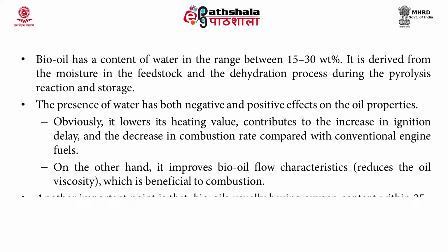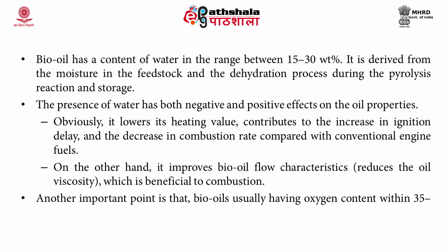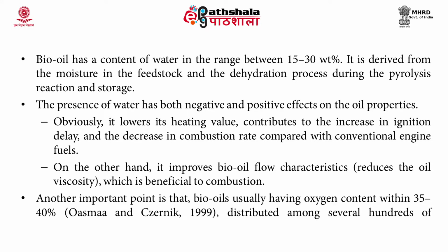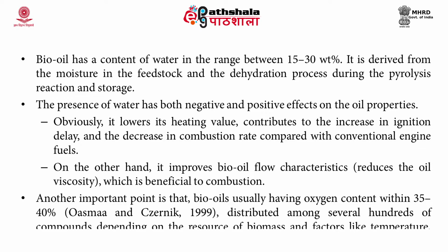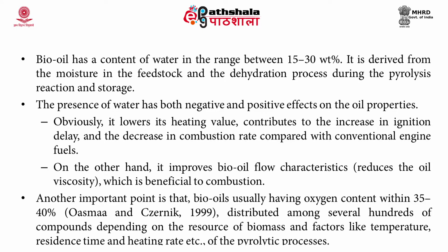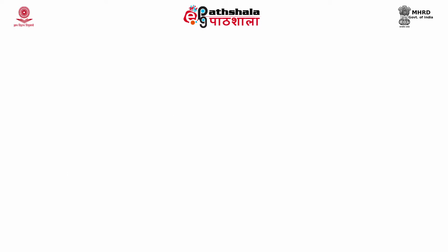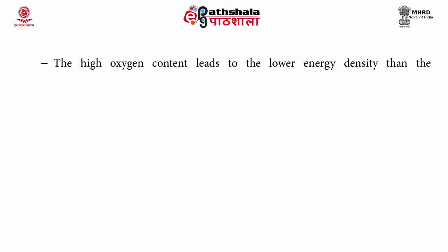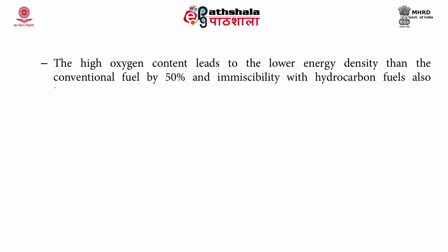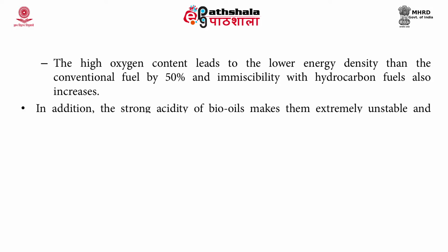Bio-oil usually has an oxygen content of 35 to 40%, distributed among compounds, depending on the biomass resource and factors like temperature, residence time and heating rate of the pyrolytic process. High oxygen content leads to lower energy density, and immiscibility with hydrocarbon fuel also increases. The strong acidity of bio oil makes it extremely unstable and reactive in nature.